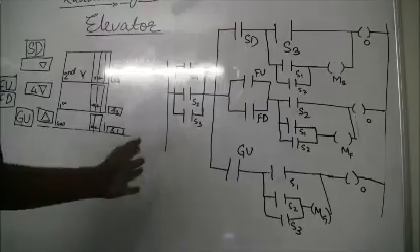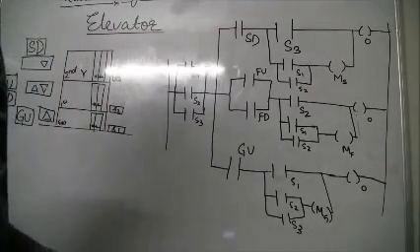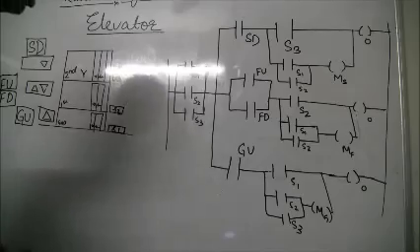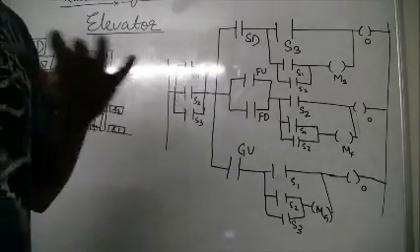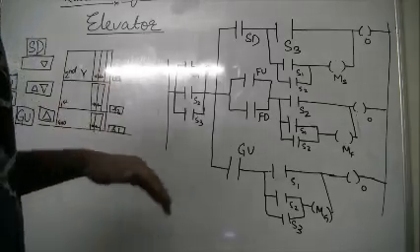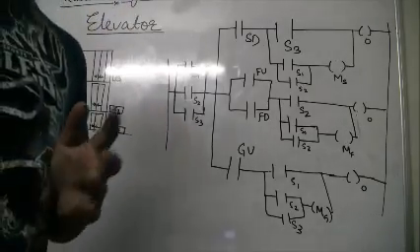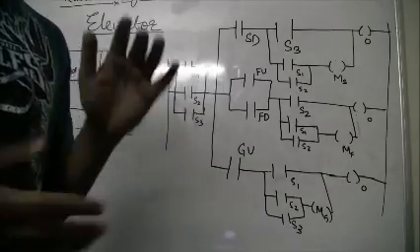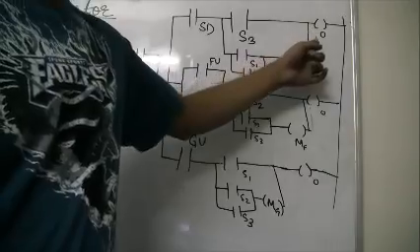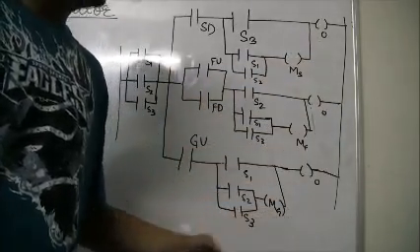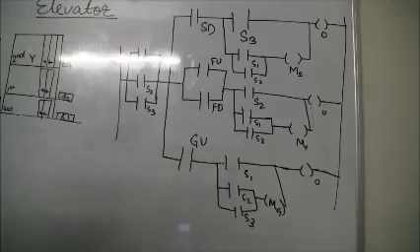So this was the second part of the elevator problem. Now, if we have to combine all the steps of the ladder, step 1 and 2 were for the opening and closing of the door. We made it in the front because we're going to use it again and again, and we made it automatic closing, so you don't have to close the door when you are in the lift, right?